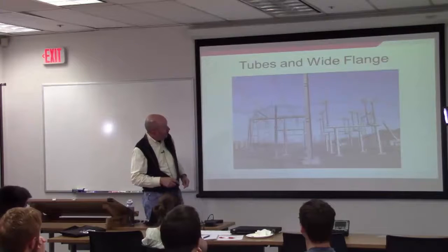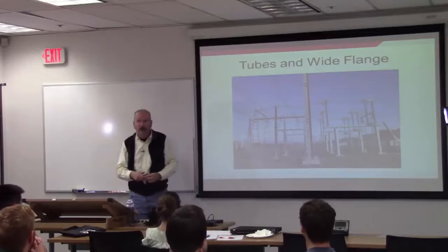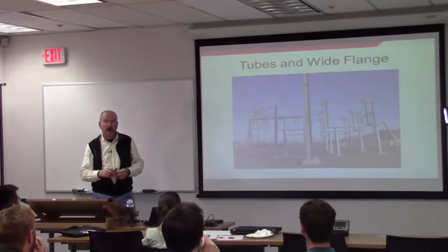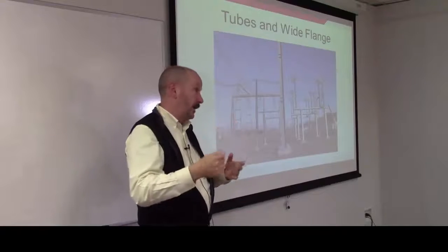And if we had a better close-up of this, when you zoom in on the attachment to the vangs, there's actually a lot of science that goes into just that attachment so that it's strong enough. So you're really getting the true strength of that member, the tension from the conductors is transferred properly to that member, and you don't just fail the thing as soon as you pull too hard at one point, because you can imagine the thing deflecting badly if you didn't design it correctly.